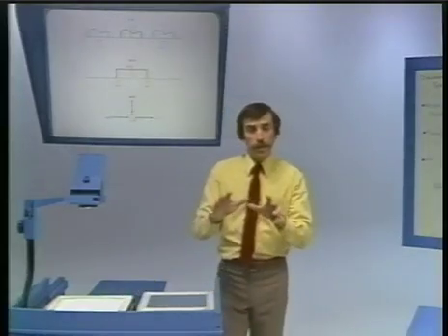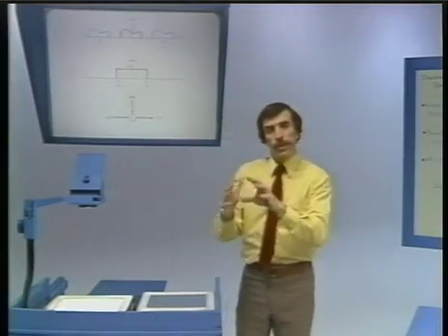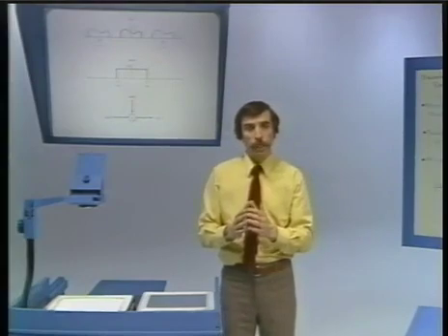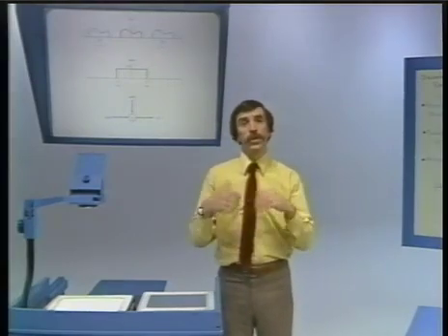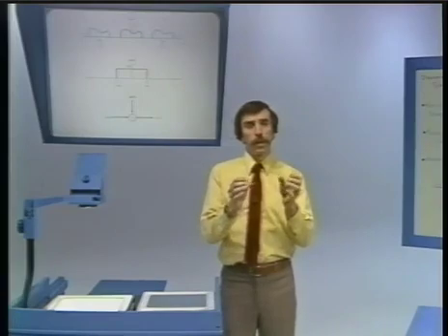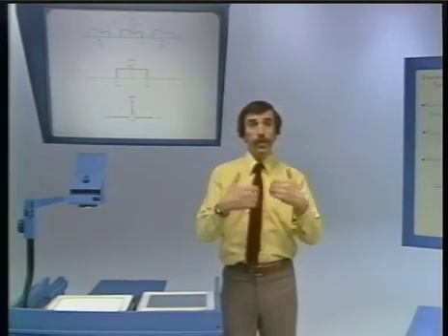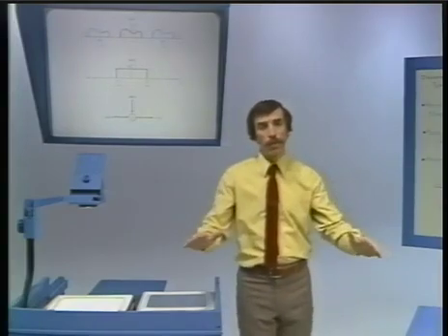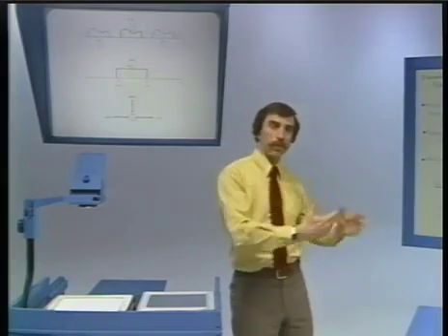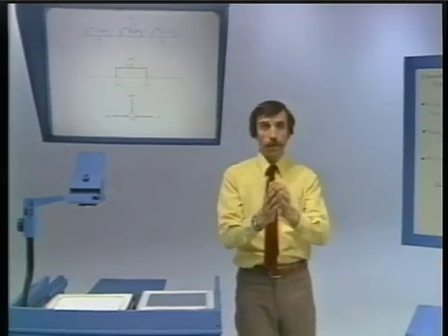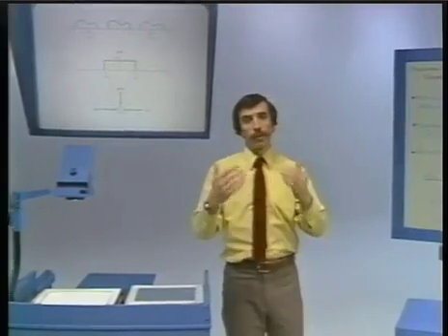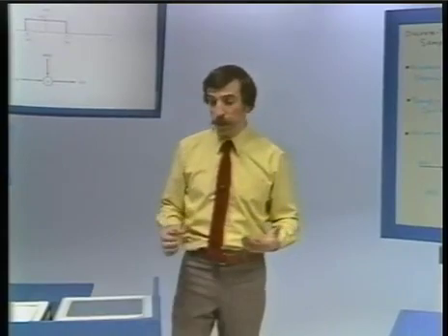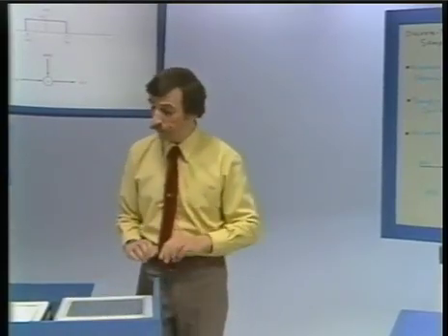Now, that's not surprising because what we've done is generated an impulse train in frequency with a certain envelope. We know that an impulse train in frequency is the Fourier transform of a periodic time function, and so in fact we have a periodic time function. We also know, from way back when we talked about Fourier transforms, that the envelope, in fact, is the Fourier transform of one period, and so all of this, of course, fits together as it should in a consistent way.